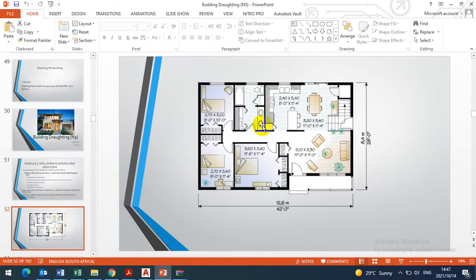It's not even fully detailed. This furniture you see here, you are going to get from the library. Why do we need the furniture? Though furniture does not count for marks, you are going to use it to gauge the room sizes, because you can't design the room size before you know the size of the bed or the couch to use. These are drawn at 1:1 size, and you get them from the library. I'm going to show you how to get the symbols. And the symbols that count for marks are these window codes.